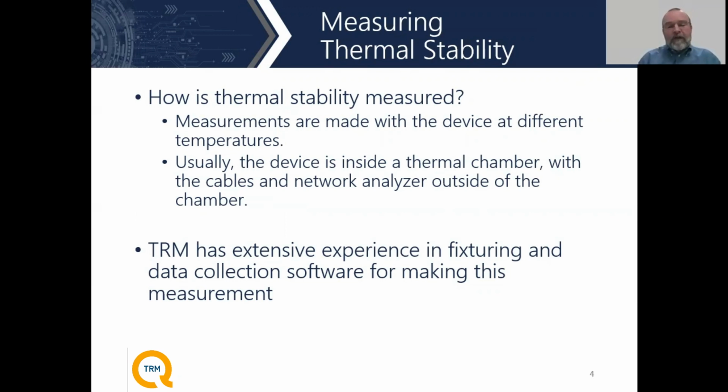Things like cables, RF cables that go in and out of devices have materials in them that are not stable over temperature, and therefore, so if we're going to take a device and put it inside of a thermal chamber and get it hot and get it cold, those cables that are connected to that are getting hot and getting cold. They're going to add error that we could attribute to our device, but they're really coming from the cables. So how do you separate that?